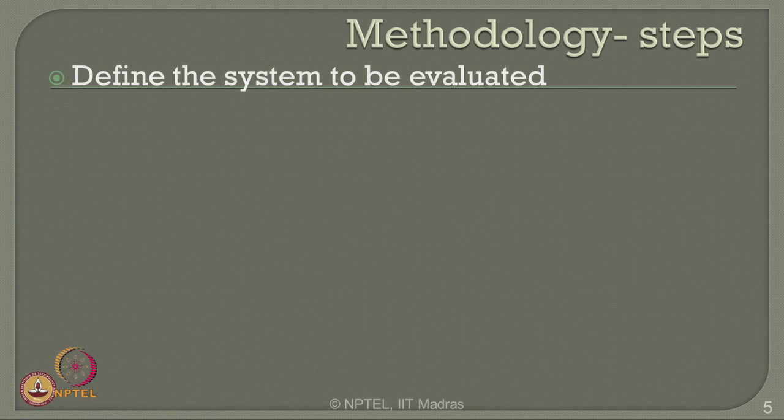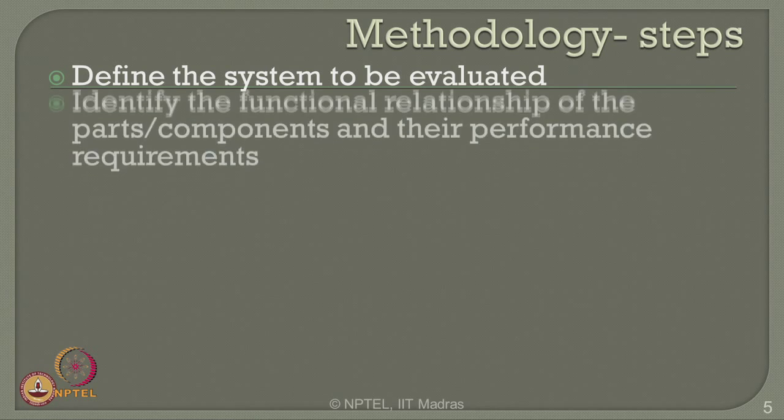Dear friends, please understand, hazard is a perceived level of failure for a given process system which is in anticipation, whereas FMEA is a prescribed level of failure analysis for a given system where the system should physically exist, not necessarily the prototype model, but at least the scaled model of the system should be available to you. Therefore, FMEA studies are generally conducted to pre-analyze the failure modes of a given product before it is marketed or before it even starts production. So, first define the system which needs to be evaluated.